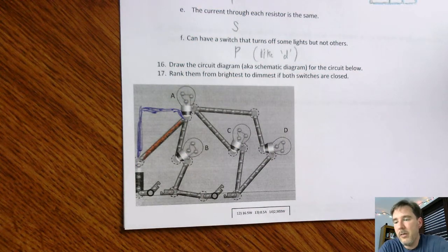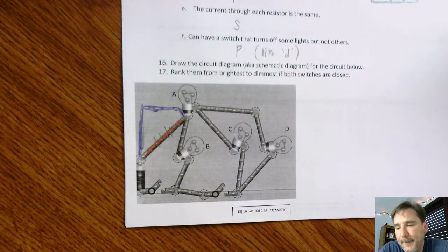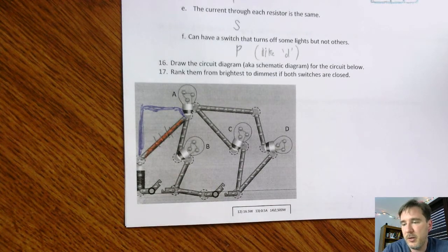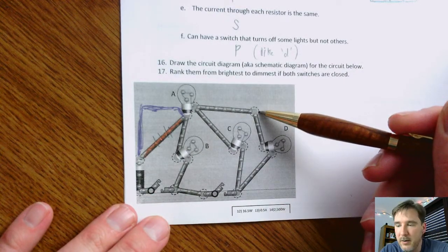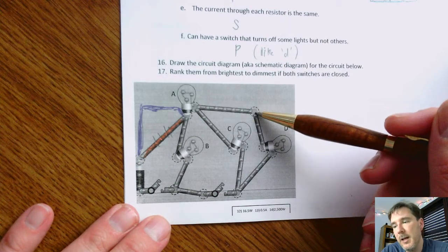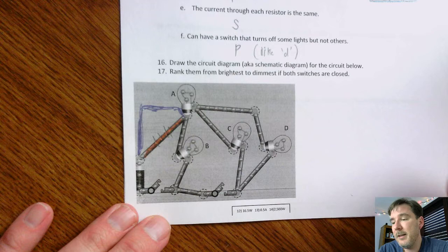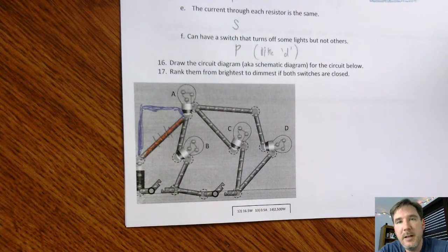You're just drawing the connection. I would not have this anymore because that would be a short circuit. But you're just drawing the connection. So don't feel like you're constrained to the geometry of the wires as they're actually there. The same thing here. I have a kink here, I have a bend here, and you don't have to have that there. You can take that away and draw a straight line, or you could add more bends. Do whatever you want to most clearly and best represent the connections in this circuit.